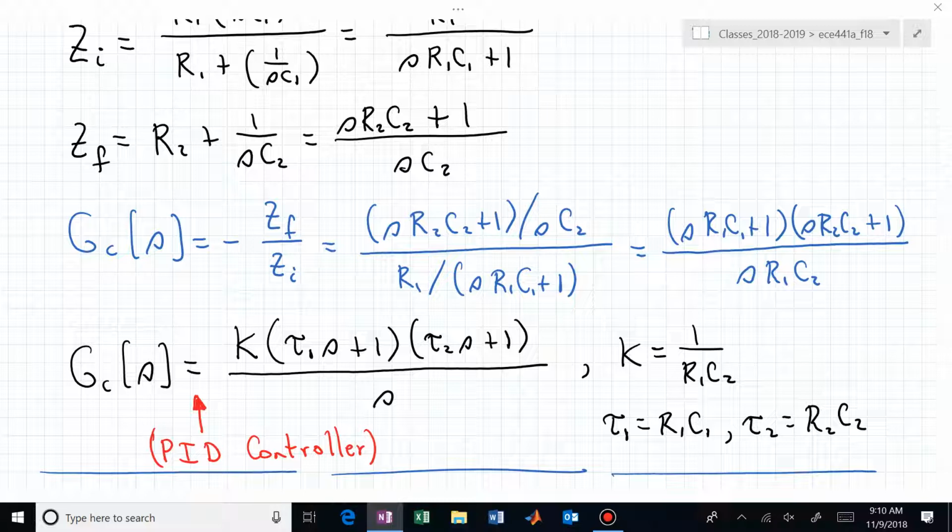What if we wanted to improve the steady-state accuracy? If we want better accuracy, that means if I put in a 4, maybe I want to lock right into that 4 in the steady state. That's my steady-state accuracy. Maybe to do that, I put in a pure integrator. And boom, that's in that PID controller. I have a pole right at the origin, but that's a phase lag behavior.